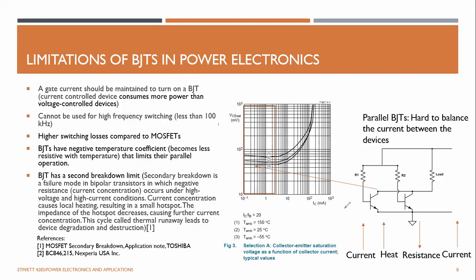Switching loss is when you switch the transistor on and off, not in the steady state. When it is turning on, in this region there's a power loss, and then you keep continuing, and in this region there's a power loss, that is the conduction loss, and when you turn off again there's a switching loss happening here, right?